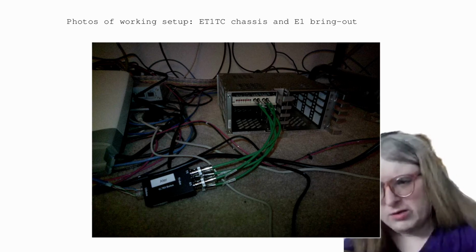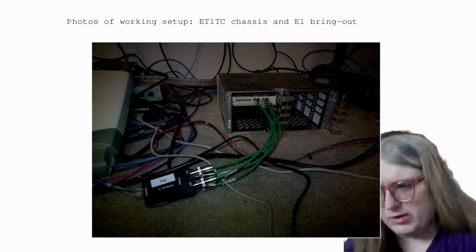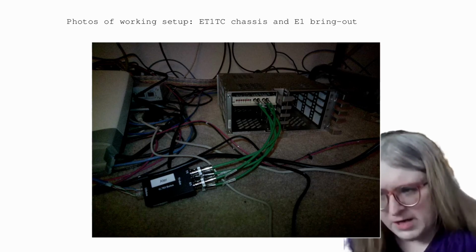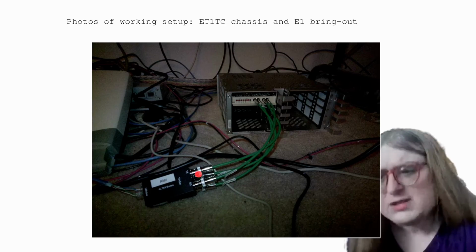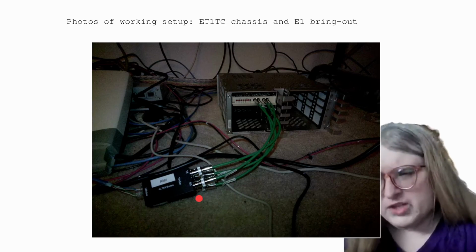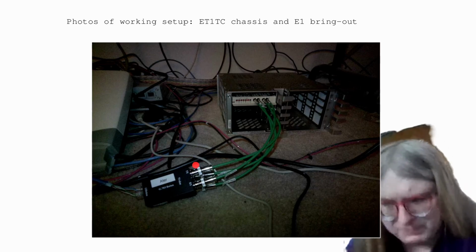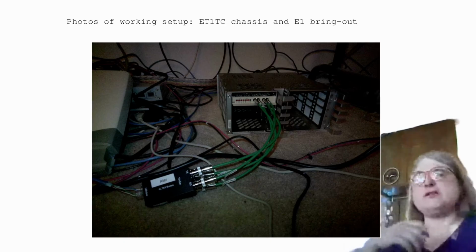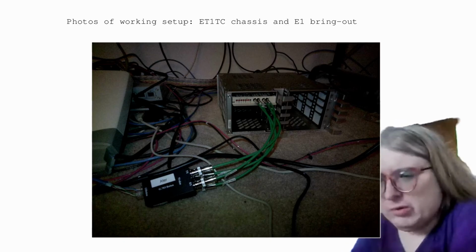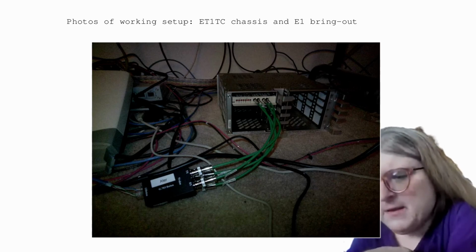If I have the ICE1 USB working with both E1 interfaces driven by Raspberry Pi 5, what if I simply cross-connect on the BNC side, TX to RX, either on the same unit or crisscross? It was actually very flaky.